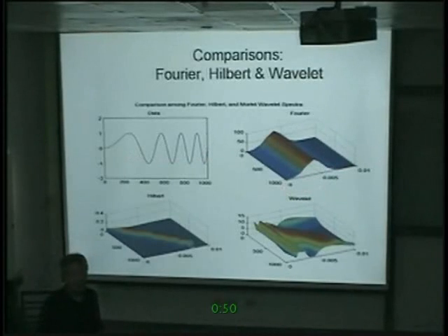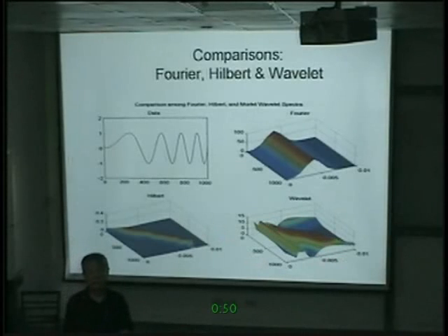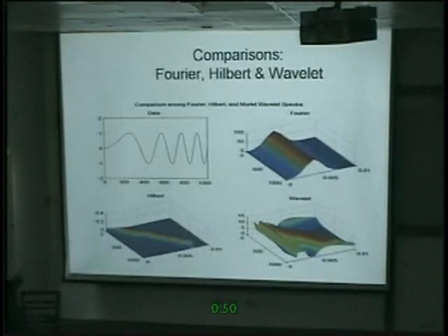And that kind of question led people to wavelet. Wavelet says, oh, Fourier is no good. We can tell you how the frequency changes. This is time, this is frequency. Wavelet gives you this kind of change. So that's why wavelet became so popular. But wavelet is again an a priori basis function, and there are lots of problems about leakage and all the other things, especially when you use continuous wavelet. It's not orthogonal, it's not energy conserving, there are lots of issues.